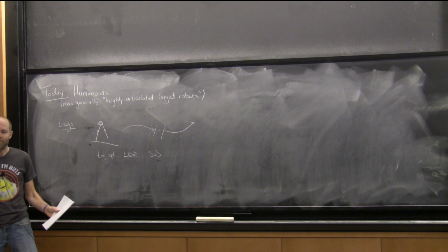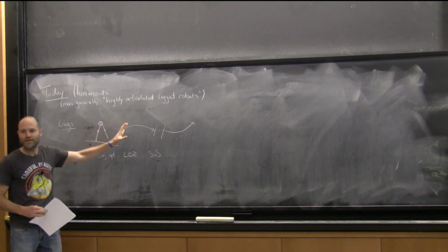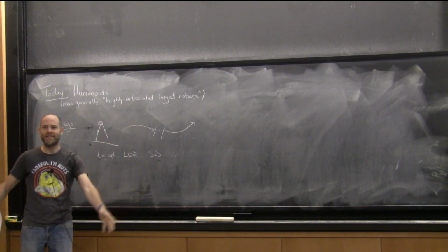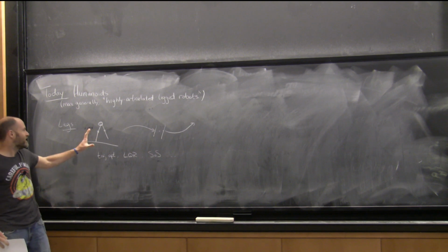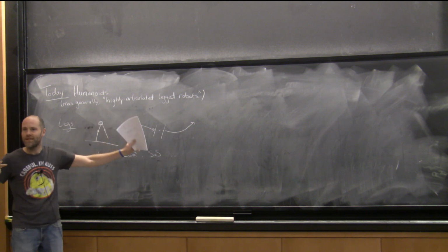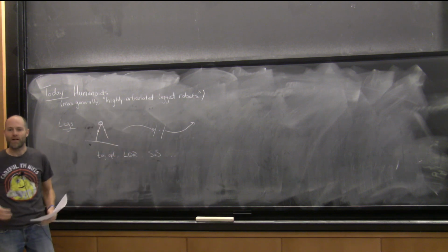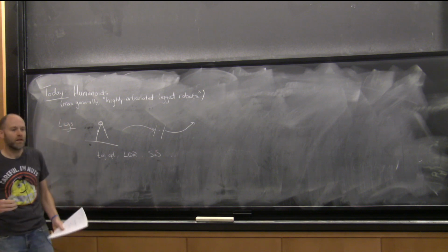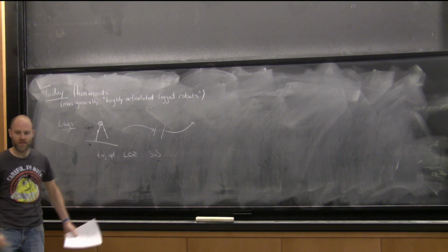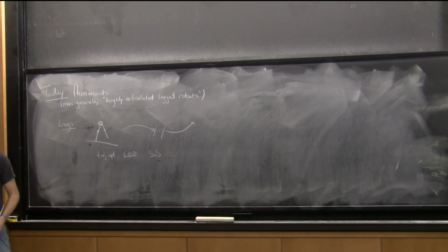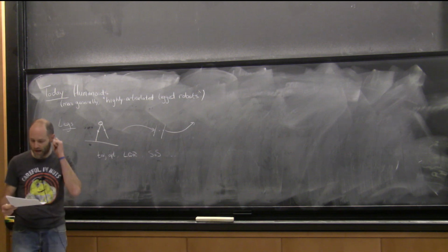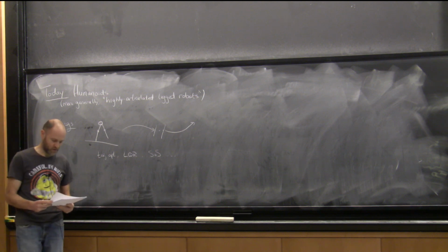As you add more and more complexity, it gets worse and worse and worse until it starts getting easy again, right? Somehow, when the robot has enough joints and enough control over those joints, it gets easy again. I want to tell you that story today to make sure you understand that there are simplifications if you can assume that you can basically do what you need to do with your foot relative to your mass. They take away a lot of that complexity and allow a 2-stage approach to the problem, and that's what's fueling a lot of the successes you see on the complicated robots.